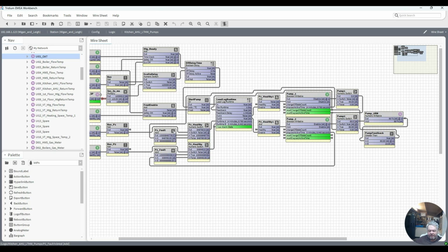If we've got a fault coming in where you're adding to the existing time clock runtime, we are adding 10 nines, so that if it's faulty, A, you won't be able to run the pump anyway because we've also tied it into this, and B, if we're selecting a pump, it's going to always select the minimum runtime, which is always going to be not the pump that's in fault.